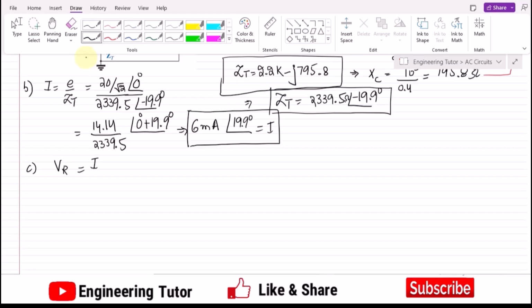Therefore, VR is total I multiplied by the value of R. Similarly, VC is current multiplied by minus j XC. The current is already known, 6 milliamps, which is 10 to the power minus 3, and the angle it has is 19.9 degrees.